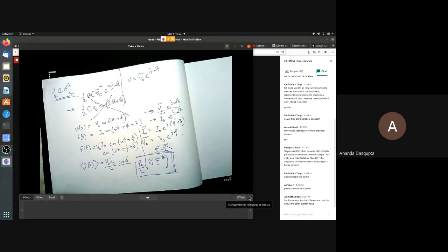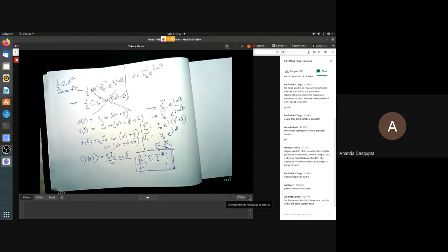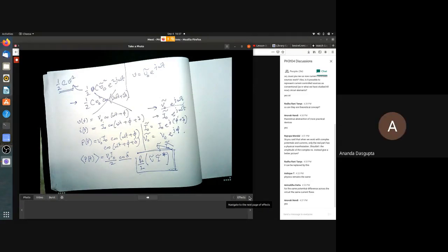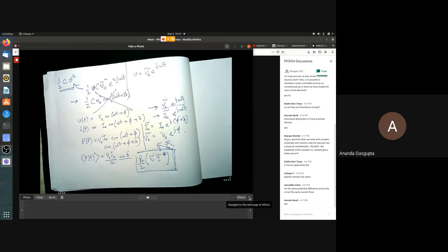Okay. Now later on, I don't know whether it's later on or even earlier, you may have already heard of the Poynting vector, right? Yes, sir. And when you calculate the Poynting vector, you calculate E cross H with some extra factors, right? But when you're talking of waves, you deal with E cross H as complex vectors, simply because, again, you take the real part. The waves are easier to describe in terms of complex exponentials. But then you would see that the formula you use is E cross H star, real part of that, by 2. Same reason as this, basically.